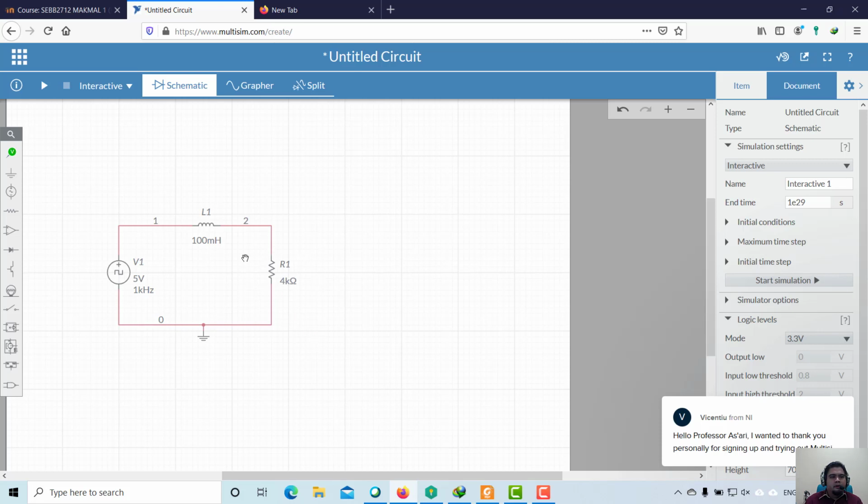In order to check the behavior or characteristic of the voltage during charging and discharging, whether in a face-to-face or practical experiment, you need to use the oscilloscope. But by using this simulator, you just need to pick up this analysis and annotation here. You just click the voltage. Actually this one represents the positive probe of your oscilloscope.